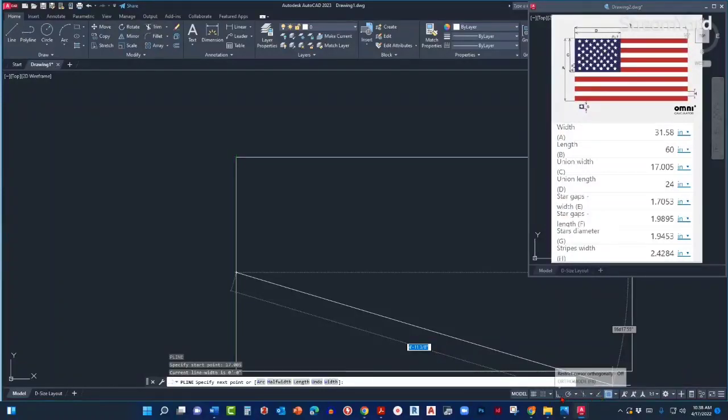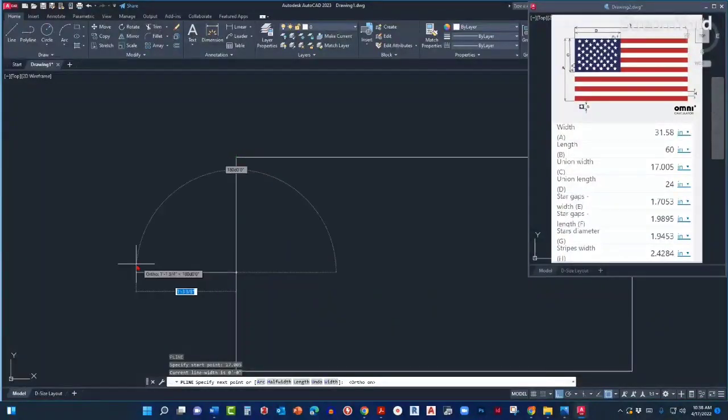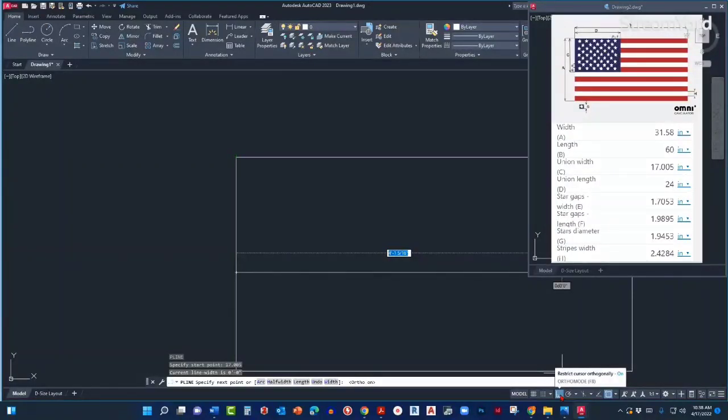In this case, it would be the ortho mode. So the ortho mode precision setting, let's activate it by left clicking on it, and again it's showing blue. It's helping us now to draw precisely a straight line. If you move it up, it's going to draw a straight line like so. So again, that's the ortho mode that is helping us right now.